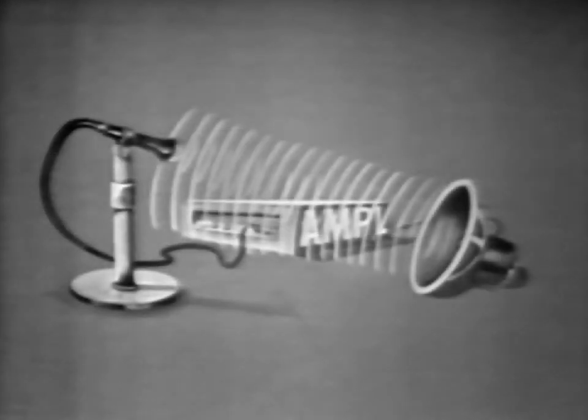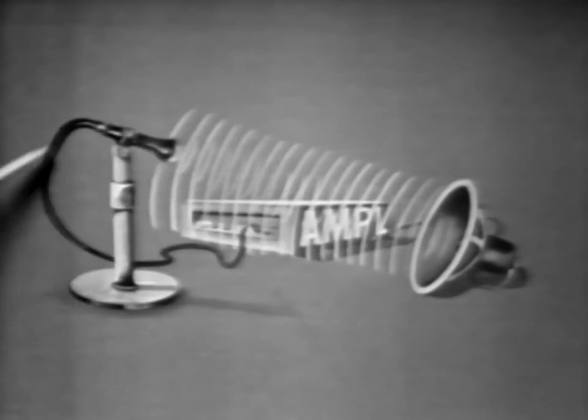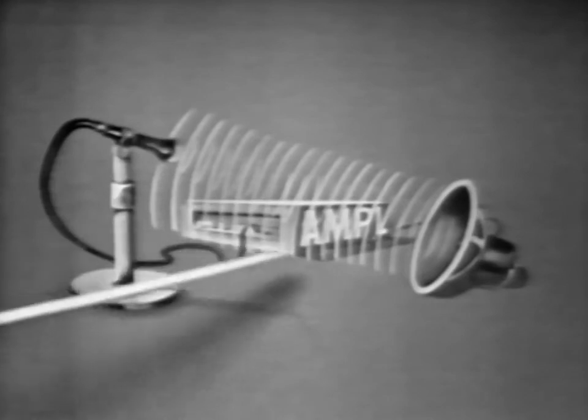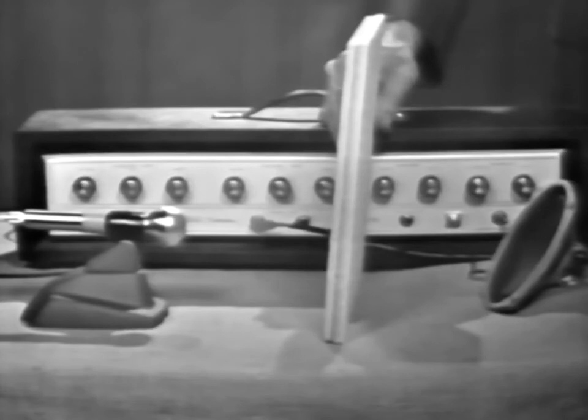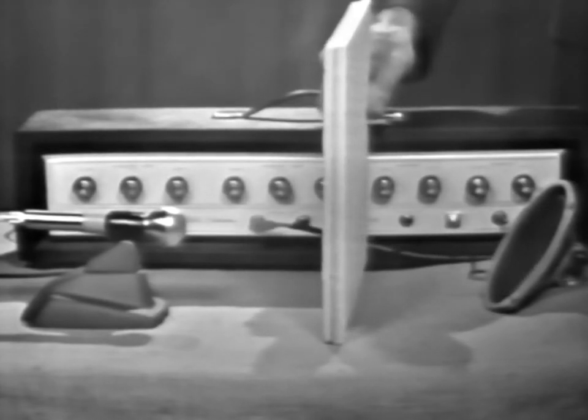Any sound picked up by the microphone is fed through the amplifier and out the speaker as sound. If the microphone picks up the sound coming out of the speaker, the output is feeding the input, and the stage oscillates. Now, since there's no way to control the amount of feedback, the strength of the oscillator signal continues to increase. You can hear this increase when we remove the tiles slowly and allow the microphone to pick up the speaker's output.